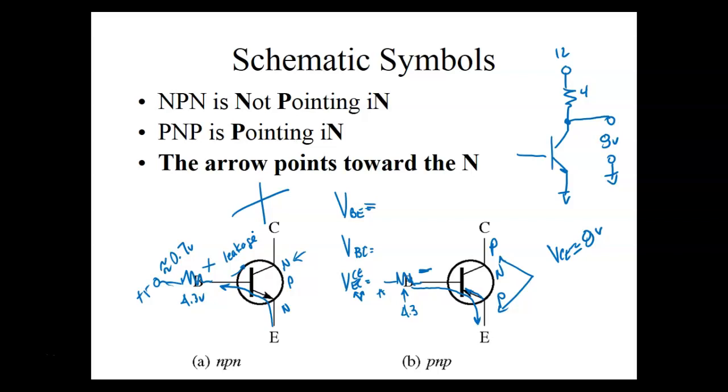But what you've got is that the base region is lightly doped. That means it doesn't have a lot of majority carriers. So all these electrons come flying in here from the emitter, and there are not enough holes to handle all the electrons flying in.